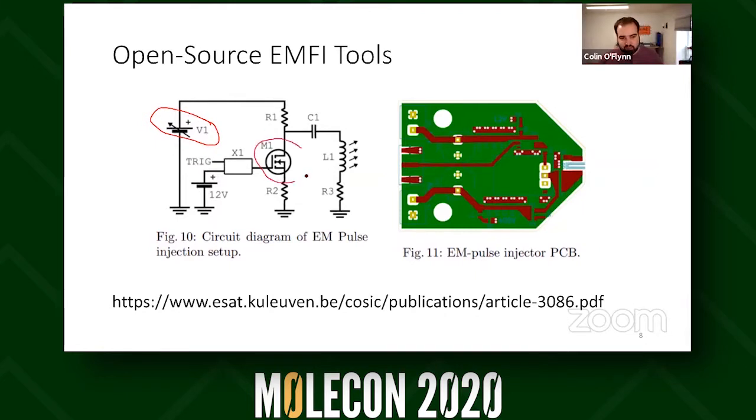You have an electronic switch that's then really quickly closing that supply to generate a strong pulse. Here they use a capacitor just to safely couple this into the inductor. So this is a low-cost architecture that's actually fairly safe. I say fairly safe because it does not have high voltages here all the time because of this capacitor. So this is really important.